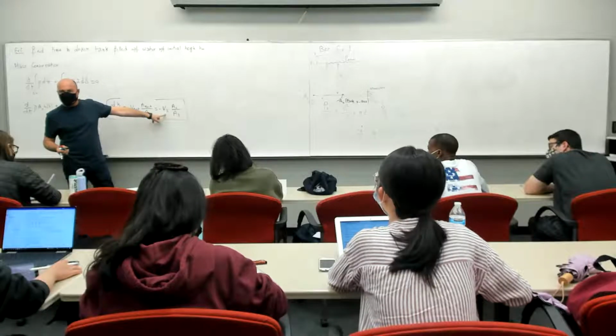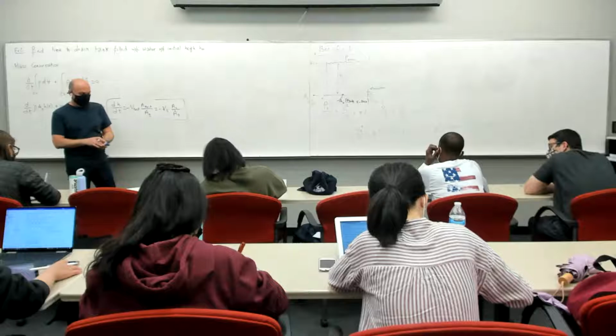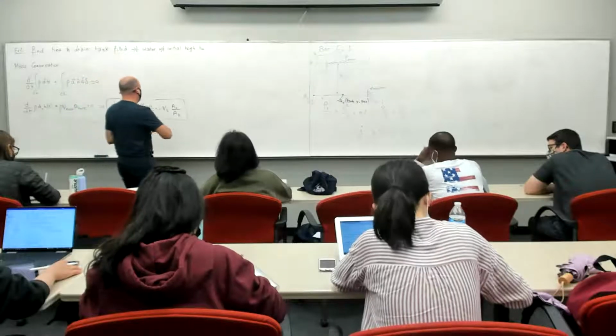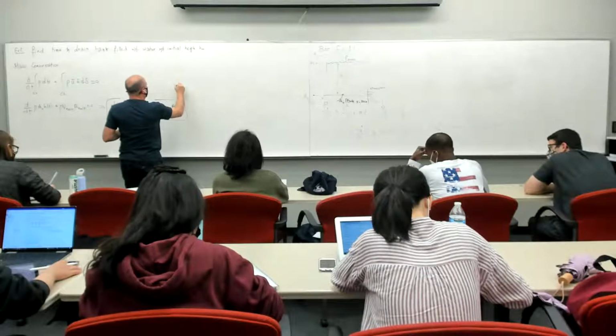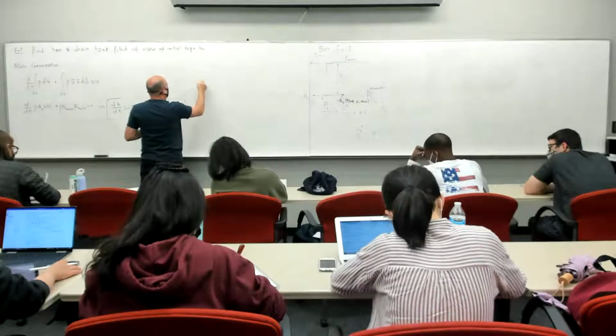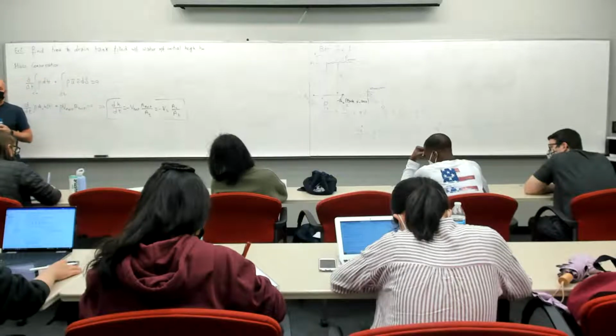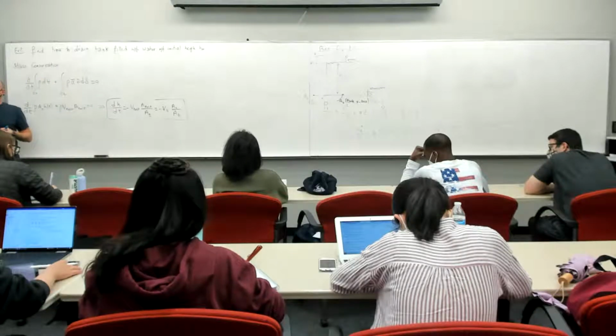Now we take that Bernoulli equation that we applied over there, for V2. For any instant in time, for any height h, that exit speed is going to be square root of 2gh.